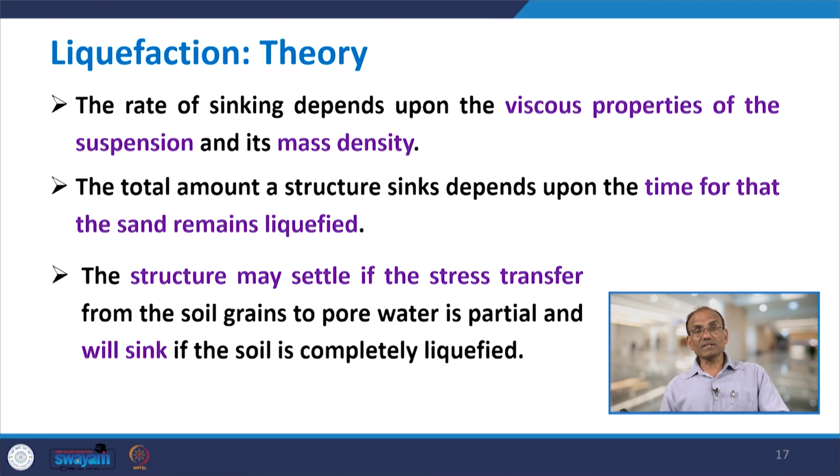The total amount a structure sinks depends upon the time for which the sand remains liquefied, because as we discussed, during load reversal the liquefaction phenomenon may be recovered, or dissipation may take place. The structure may settle if the stress transfer from the soil grains to pore water is partial, but the structure can simply sink if the soil is completely liquefied.